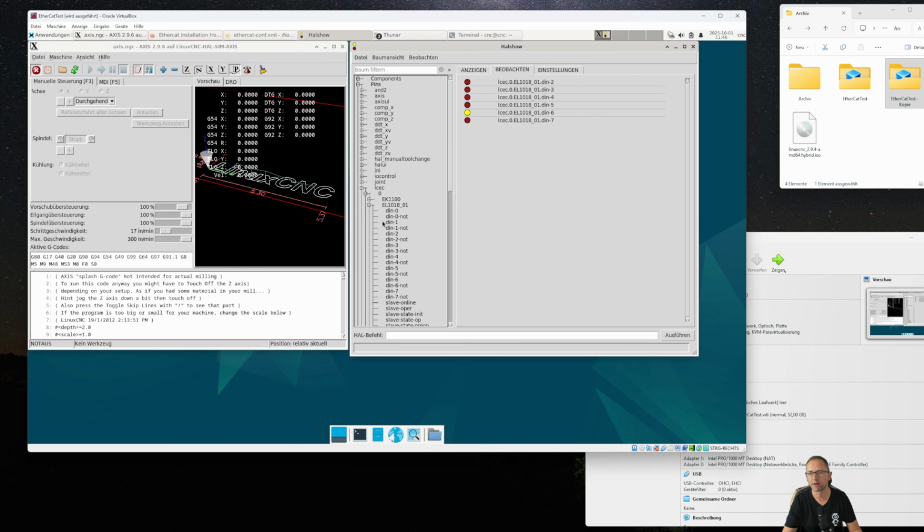We can click on these pins here, and I would like the 4 outputs as well. There. I did the following. I have now connected the input module with the output module using a bridge. And if I set an output somewhere here, then the first pin on the last input module, this one here, should change. This is simply the wire bridge that we see here. That means the output bit dampens the input.